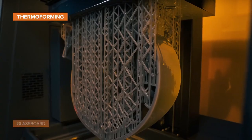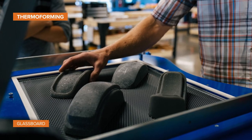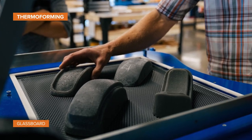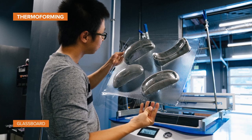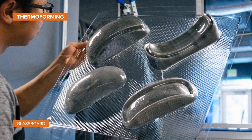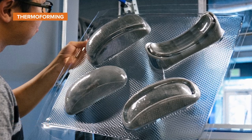Product development firm Glassboard leverages the printing speed of draft resin to quickly produce molds and thermoform polycarbonate prototypes such as helmet shells or packaging. They can achieve complicated mold shapes that would be difficult to manufacture traditionally, including small features and holes for an even better vacuum distribution across the surface.